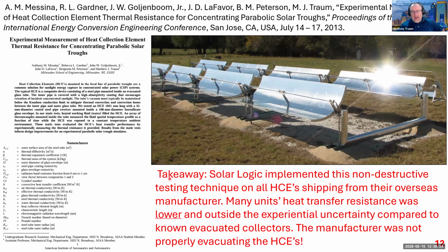And the takeaway is that Solar Logic implemented this non-destructive thermal testing technique on all of the HCEs that got shipped from their overseas manufacturer. And the company found that many of the units' heat transfer resistance was lower and outside the experimental uncertainty compared to the known evacuated collectors that we tested that were manufactured in the US.